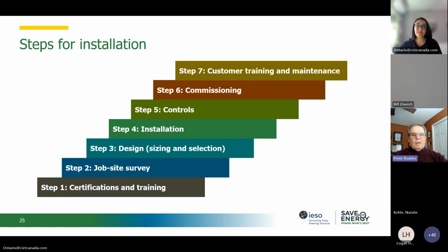For heat pump systems, knowledge of refrigeration, sizing, air distribution and controls are critical components of a heat pump installation, especially in the hybrid scenarios. Selecting the right type of control, wiring, programming, system, and changeover temperatures is critical to optimizing the efficiency, comfort, and operating costs.